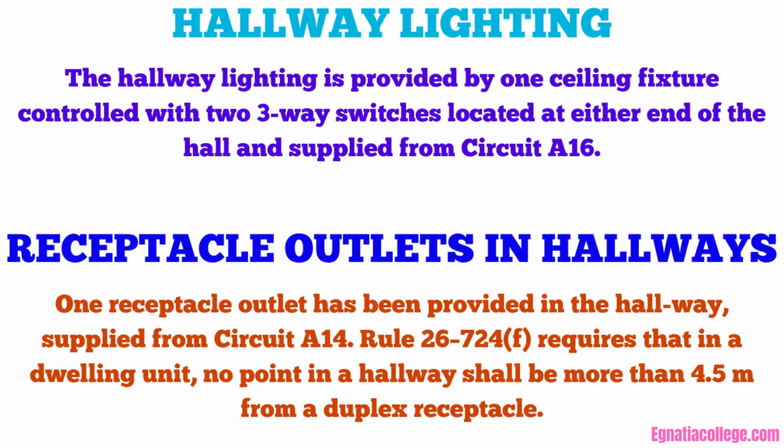Hallway lighting. The hallway lighting is provided by one ceiling fixture controlled with two three-way switches located at either end of the hall and supplied from circuit A16.